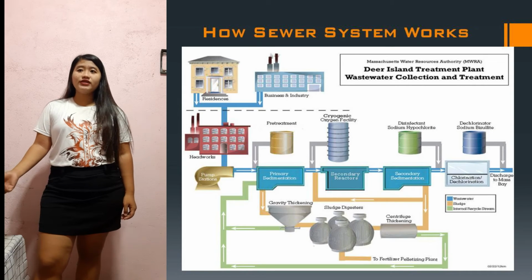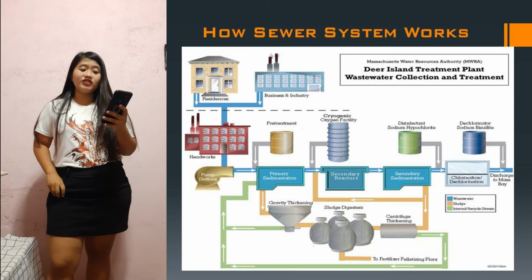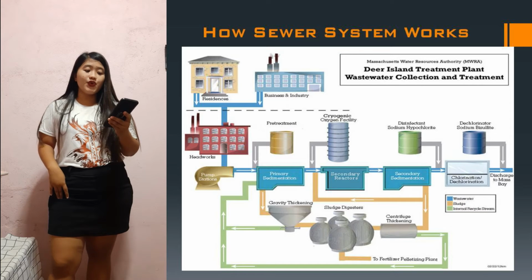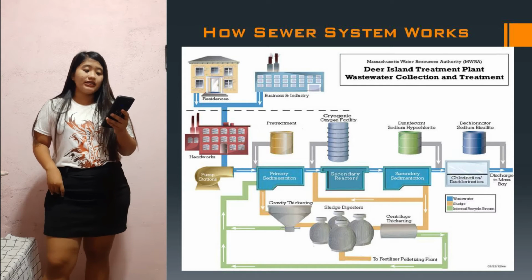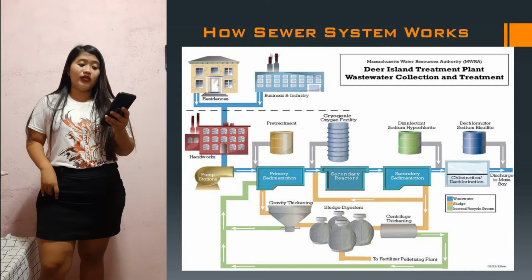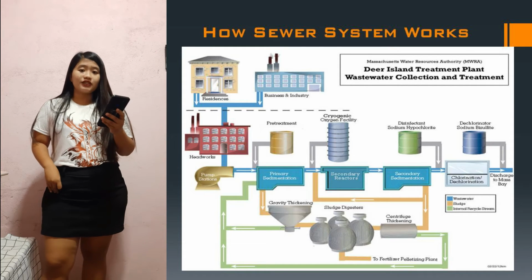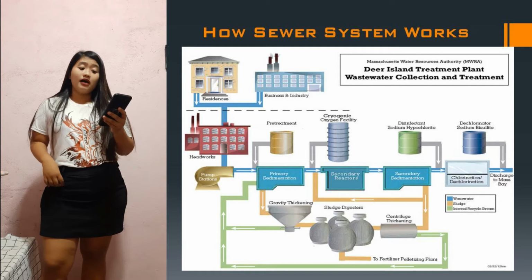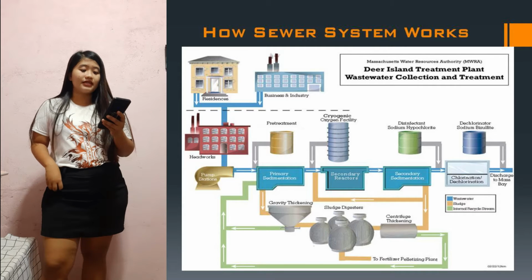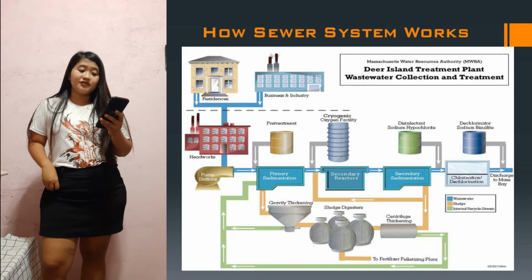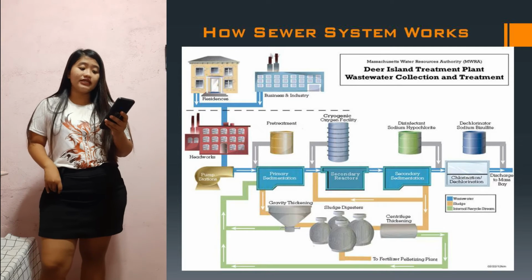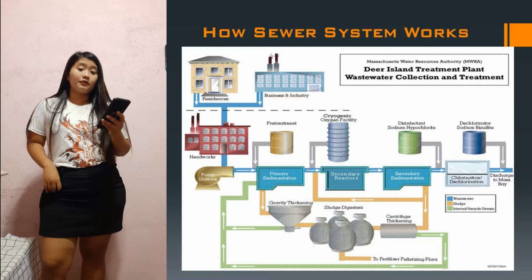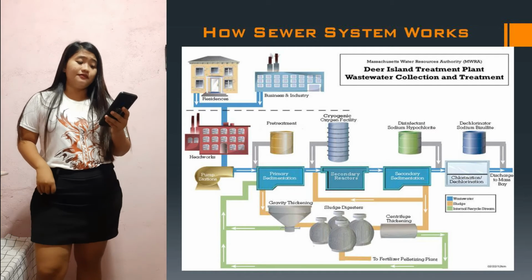And this is how sewer system works. First, sewage is pumped from buildings and homes through pipes that transfer the waste to filters that separate large objects from the sewage water. Large items can include plastic, logs, and other materials. Next, mud, sand, and smaller materials will settle in a grit chamber. These materials are retrieved over time and taken to a local landfill for proper disposal.